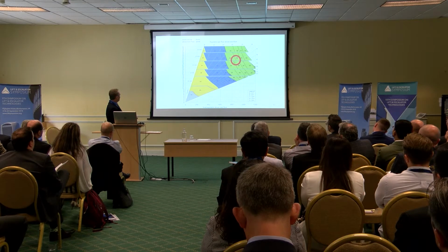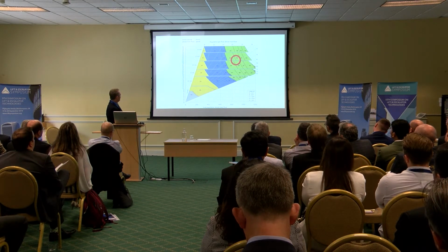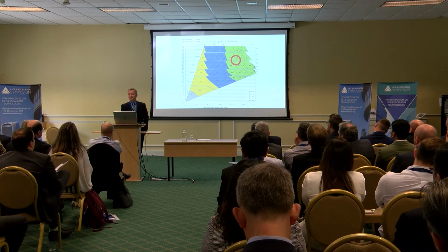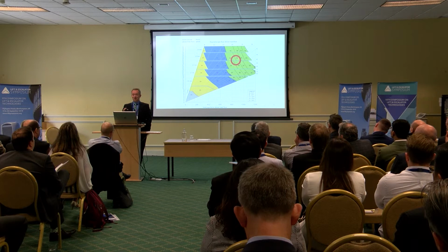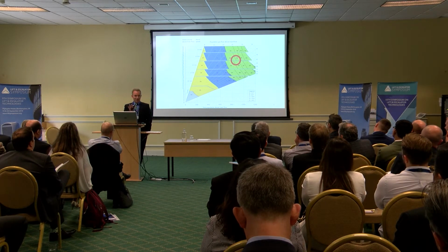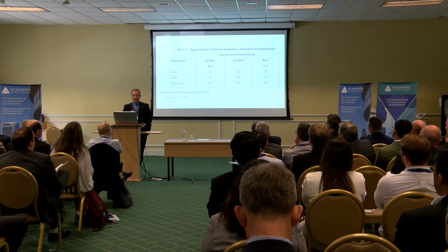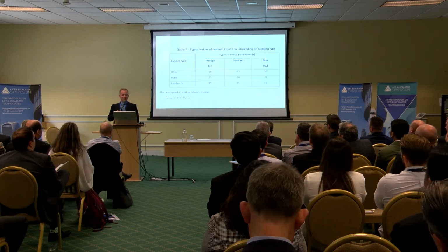But actually, if I'd considered the 3.5 metre per second lift, I could have kept with a smaller car. So I think a real designer, a real human, would take a wider range and would consider more speeds.